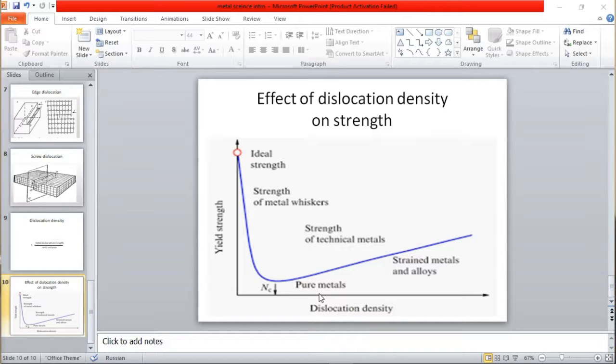But as we add alloys, the strength increases. Generally, the graph starts to increase as we have alloys. Note that the minimum value happens with the pure metal, a 100% clean metal. All metals are weakest when they are pure. That's what this graph is showing us, guys.